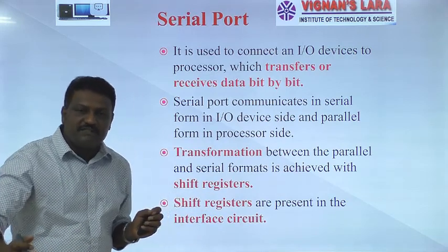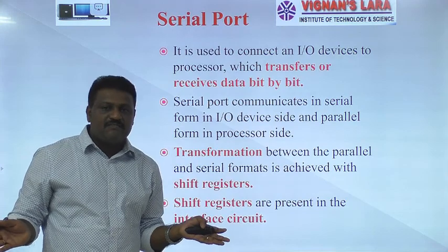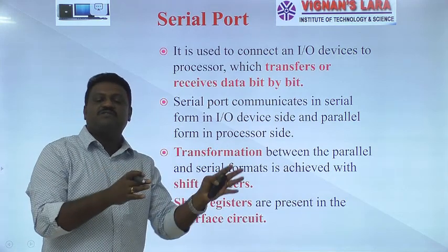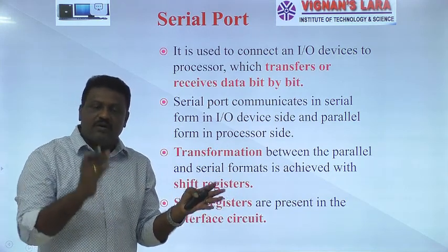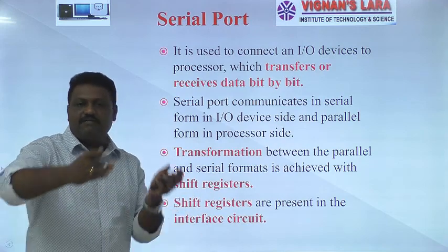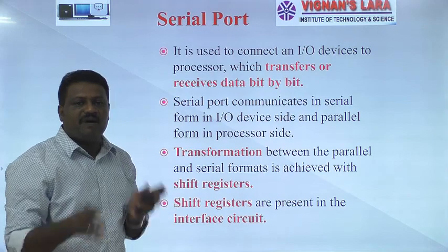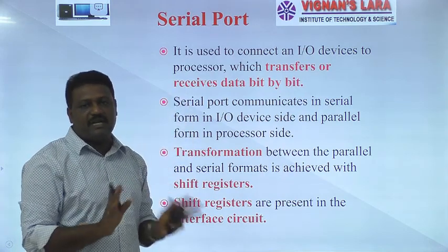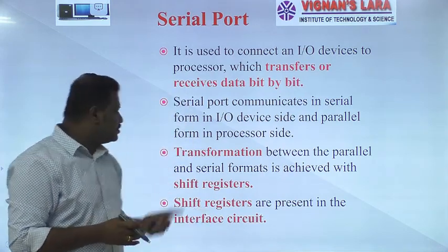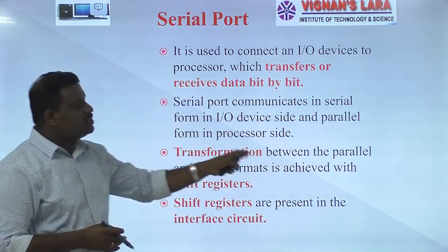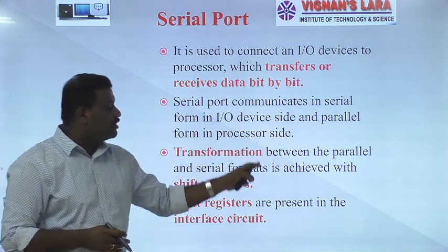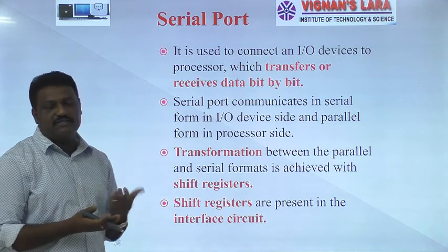But coming to I/O devices, some are parallel devices and some are serial devices. So once your device is a serial device, your I/O interface communicates with that external device in serial form, but with the processor in parallel form. That is the meaning of this. The transformation between the parallel and serial formats is achieved with shift registers. Absolutely.